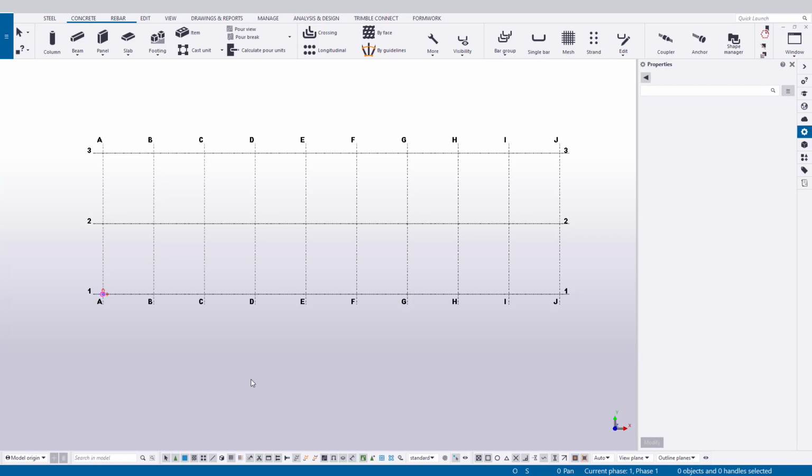Next, we need to have Select Reference Models turned on from the selection toolbar down below. If it's not, go ahead and just click the icon to turn it on. Then, afterwards, ensure you click the arrow icon to the left of that toolbar so that you can still interact with other objects. Thirdly, we must ensure that we have Selecting Components as our selection type. This is represented by the green icon with a gray triangle and circle inside of it. If this isn't active, activate it now.